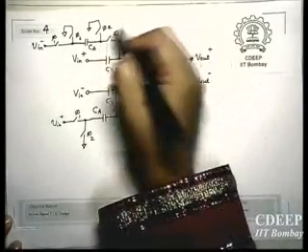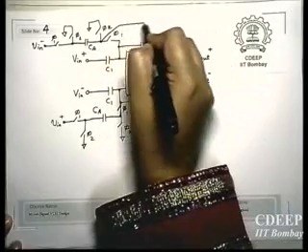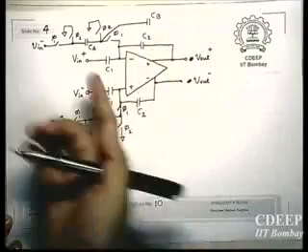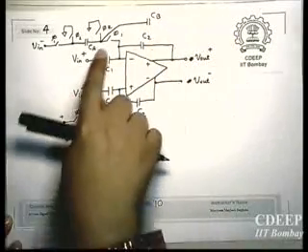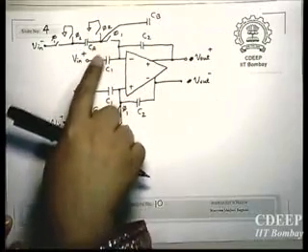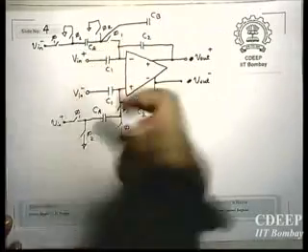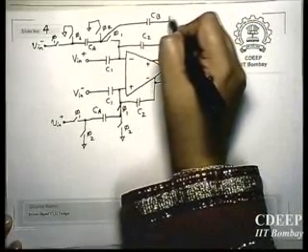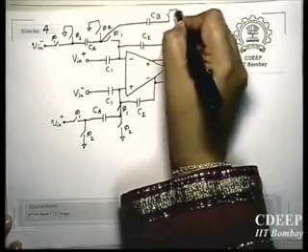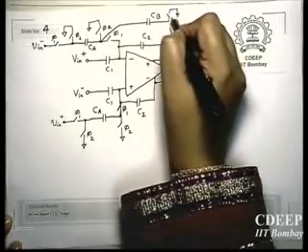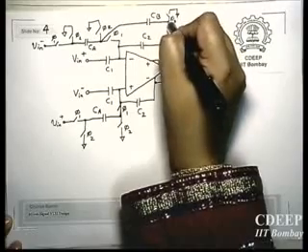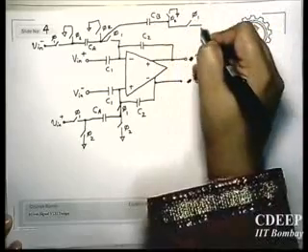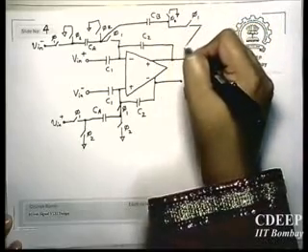We use switch sharing, therefore here we will have a direct connection of CB. In fact, the switches on the left side of CB are not required, we already have two switches for CA, the same will be used for CB. Only on the right side we will have one for ground, phi 2, and one for phi 1 which will be connected to the output.